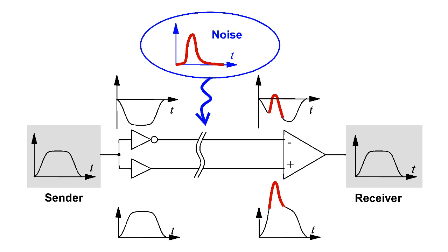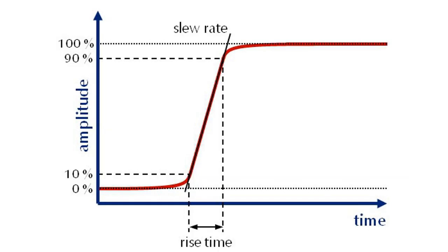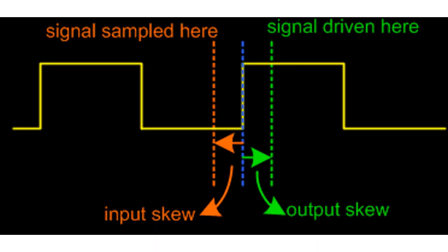Signals take finite time as they travel on a PCB from source to receiver. If data signals and clock signals do not match in overall delays, they would arrive at different times for detection at the receiver, and this would cause signal skews, and excessive skew would cause signal sampling errors. As signal speeds become higher, the sampling rates are also higher, and allowable skew gets smaller, causing a greater propensity for errors due to skew.